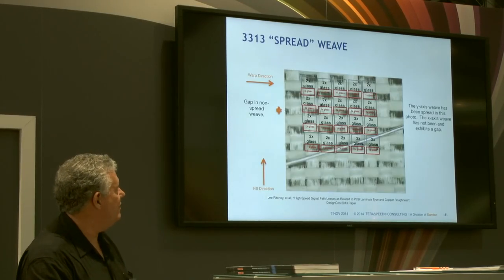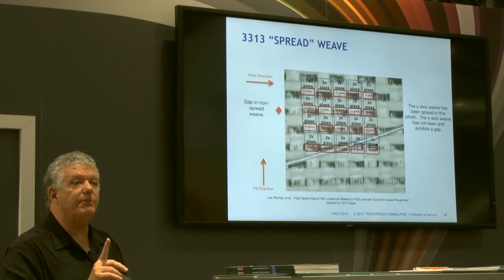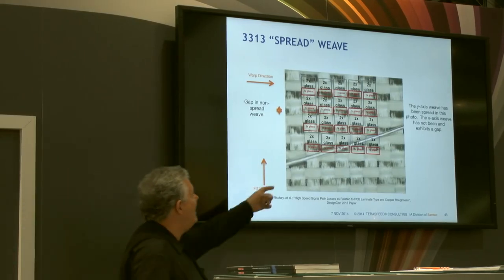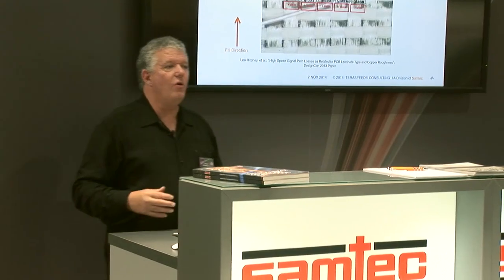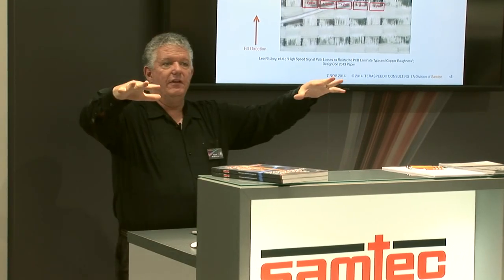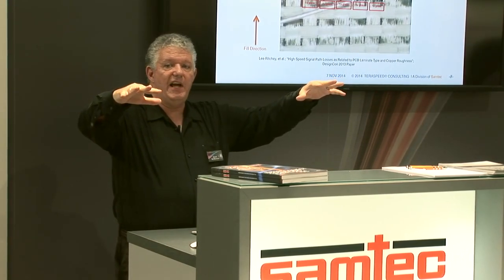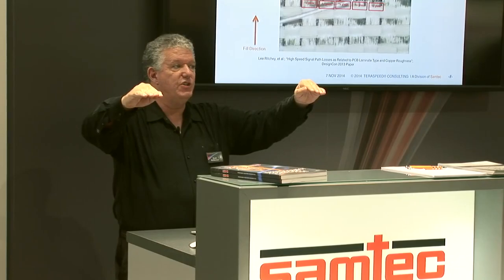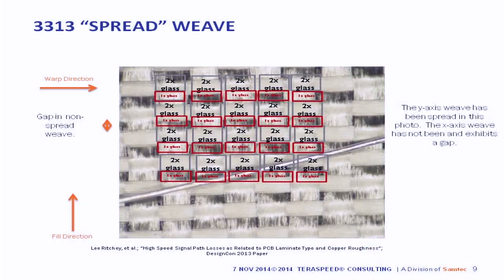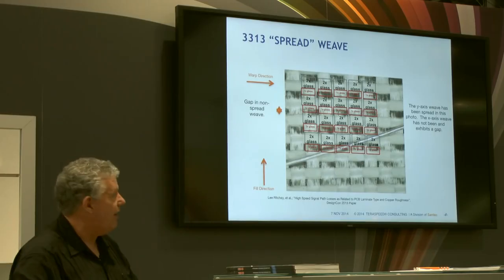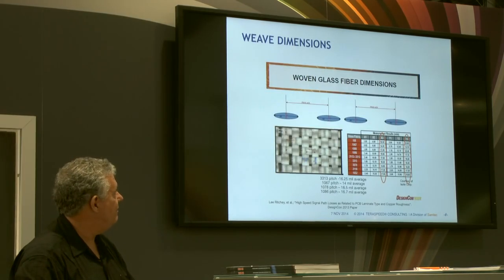We go backwards. It also solves the mystery. So why is this hole here? The hole is there because when we put the fibers under tension, the individual strands in the fiber bunch back up. We spread them out, we put them under tension, and they pull back together. So that is what's creating this variation in properties across the material.